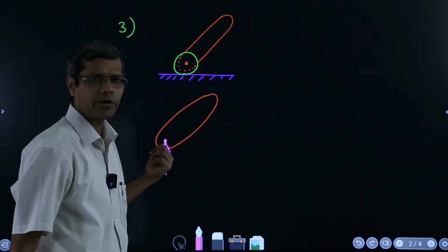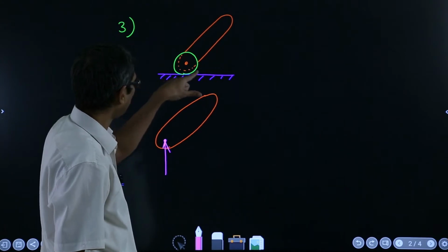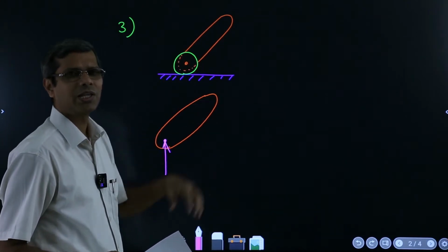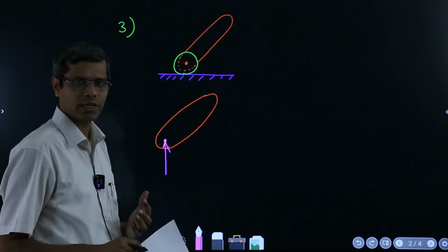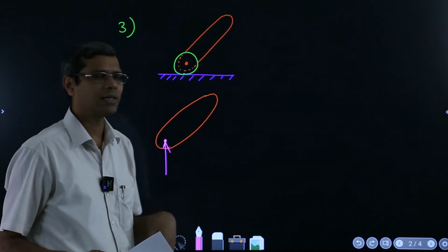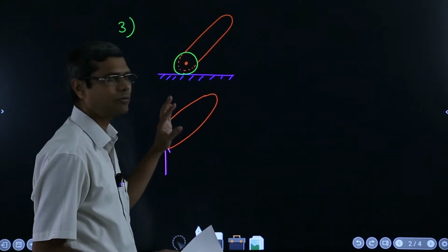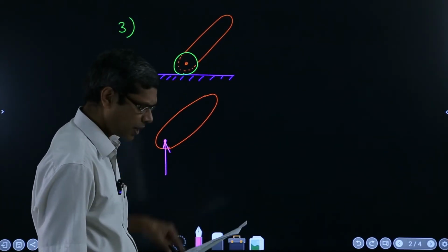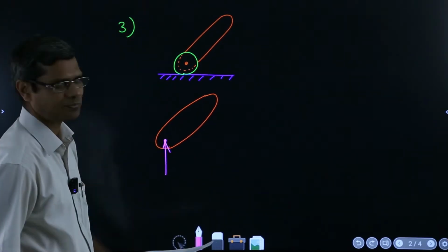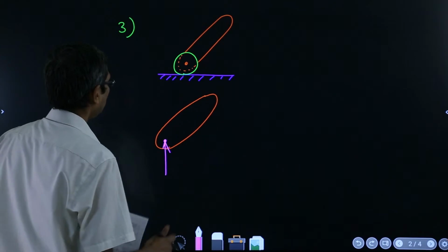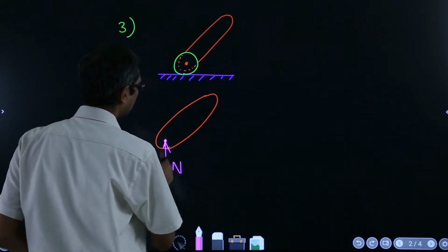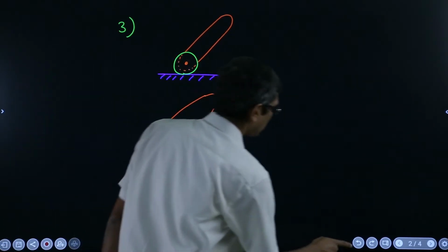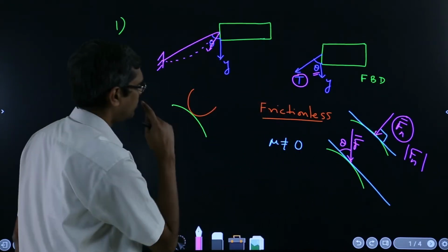this again is like the previous point which we discussed, right? So here the points of contact are frictionless. Whenever this roller support is given, you have to almost always assume that it is frictionless, very rarely it will be mentioned that there is friction in the roller. Otherwise you will have to assume that it's frictionless, and then when it is frictionless, the force will just be coming upwards. Okay, so that's how you will have to show the reaction, or a force, when you remove this connector.